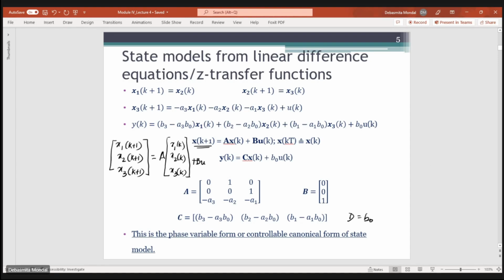So if you have some kind of transformation applied on this value of A, and you apply the same kind of transformation for all of these, keeping the initial difference equations, the initial equations which were governing the dynamics of your system, the same, the values of A, B, and C can be different. Okay, but the only thing that remains constant is the state variables, that is the values of x1, x2, x3. In this case we have 3 state variables, so these remain constant, but the values of A, B, C can be different depending on how your system is connected and in which form you are expressing your final state space model.